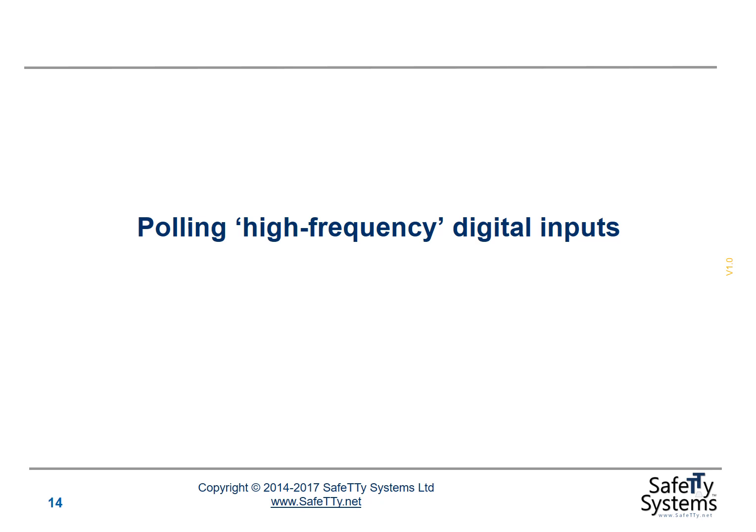Let's look at another example. So we talked about reading the state of a switch using polling. That's a pretty straightforward process. If we assume that the switch is pressed by a human being, then typically the user is going to press that button and wait for several hundred milliseconds for a response from the system. If the system responds within about 50 milliseconds, as far as most human users are concerned, that's pretty well instantaneous. So somewhere between 20 and 50 milliseconds, and the system response will seem fast to a user.